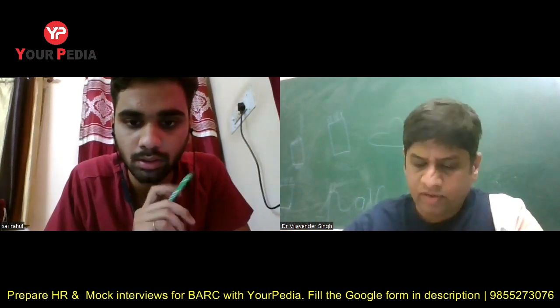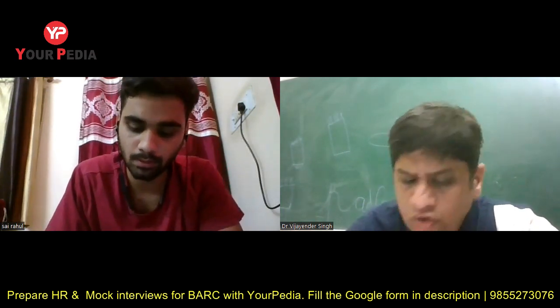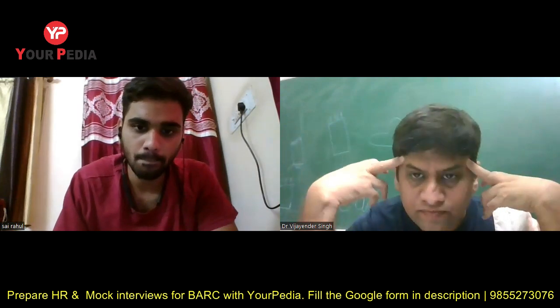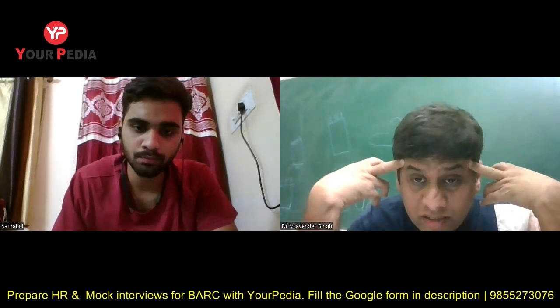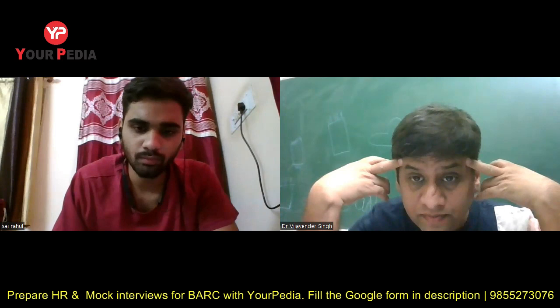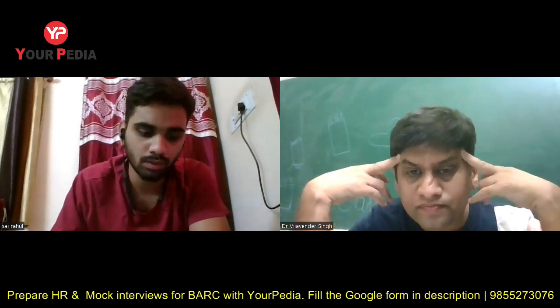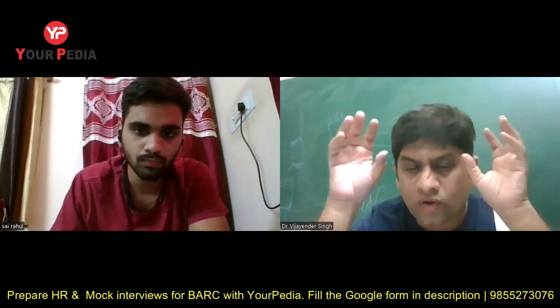Okay. Rahul, let me give you the feedback now. You need to revise the concept of available energy, unavailable energy, and irreversibility. Irreversibility is T naught into delta S generation. Delta S generation means delta S universe, which means delta S of system plus delta S of surrounding. So for calculating irreversibility, all you need to do is know the ambient temperature T naught and the entropy change of system plus surrounding.